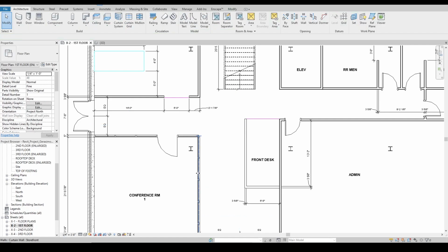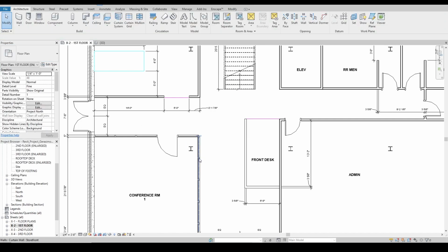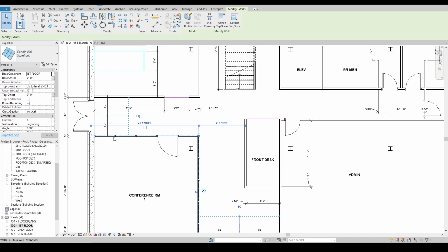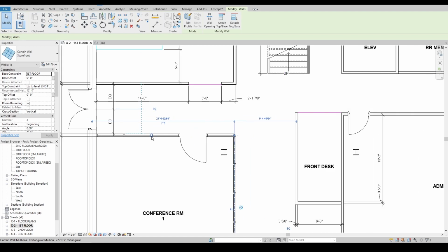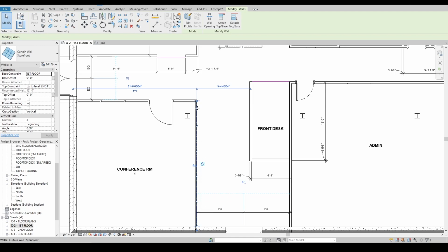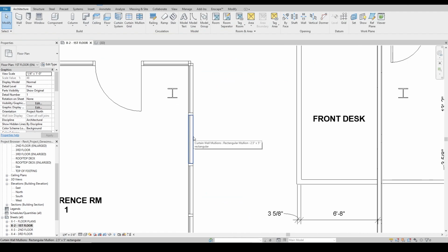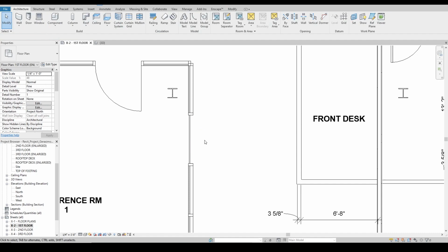And the way you go about creating one is you go to your walls, and you will see at the very bottom there are 3 different types of curtain wall. The one you would like to use for this one is the storefront one. You don't have to worry about the spacing of these things, the rectangles, which are called mullions. But once you do go into and create a box that has the curtain wall around it, you need to create a door. And the way you go about doing this is essentially hover over one of the rectangles, the bottom one preferred. You'll see there's a pin. Unpin it and delete it.